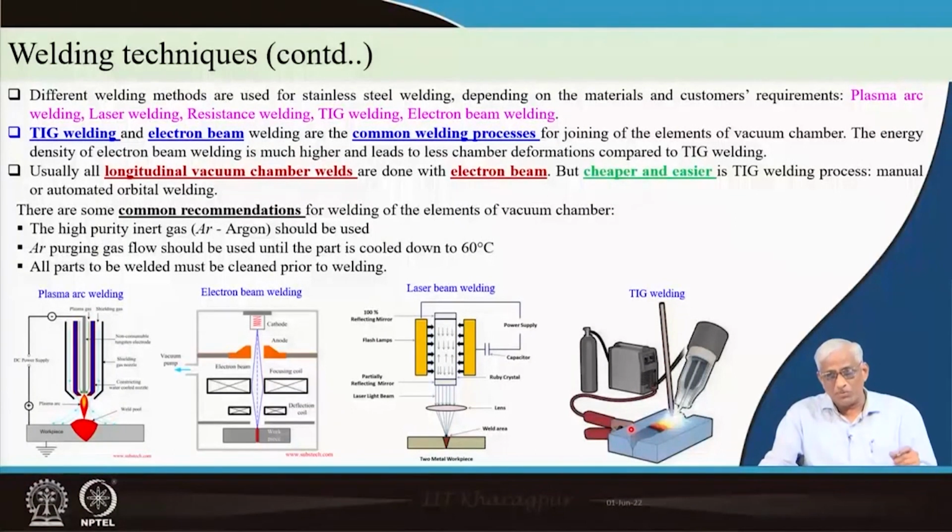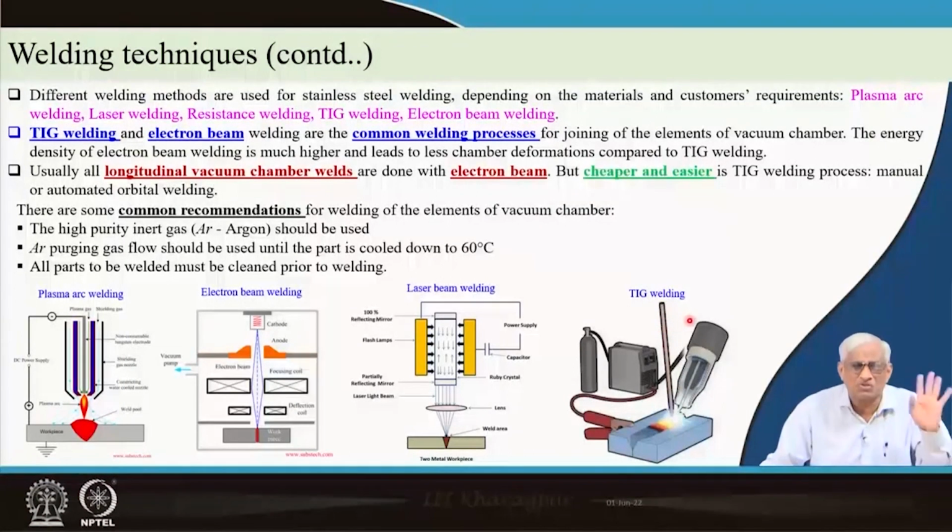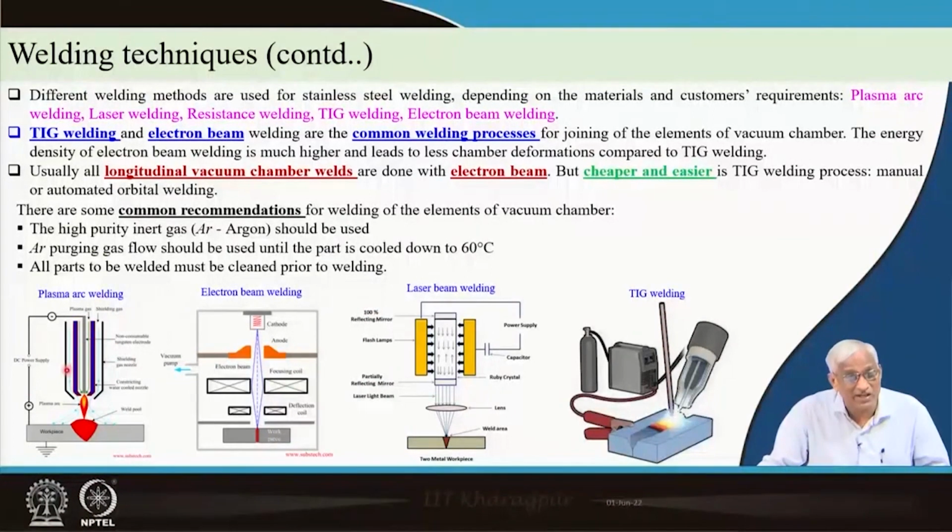Sometimes you may have to add a little bit more material by additional rods. All that technology is very well known to most of the welders. But what is not known to most of the welders nowadays is plasma arc welding, where with a high voltage a gas is coming from inside with shielded gases, and suddenly because of these voltages a plume is created, that is plasma, and finally that plasma touches the jobs to be welded in a butt joint, and heating takes place, enormous heating, and in stainless steel with bad conductivity, that heat will be retained there locally, so that it will not be conducted away, and that way you will get very good quality welding.